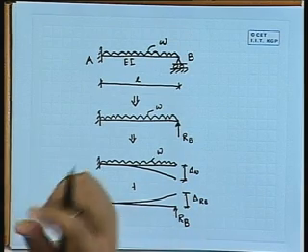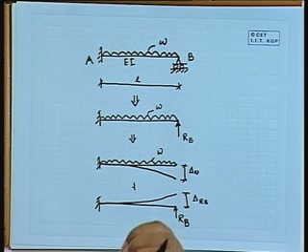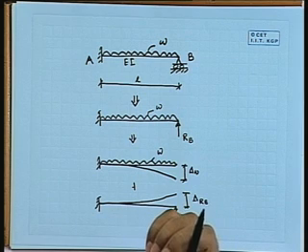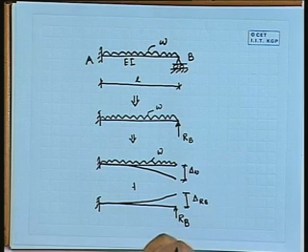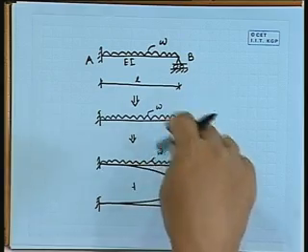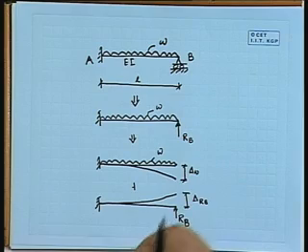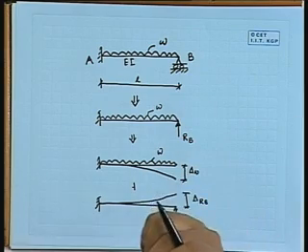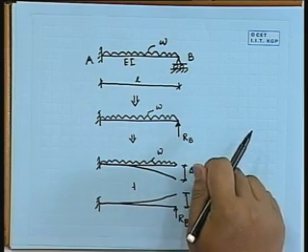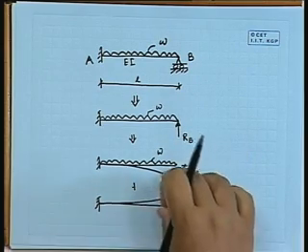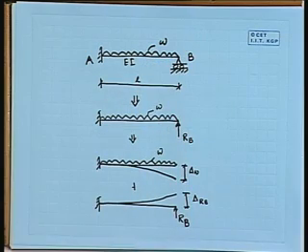These two values should be equal and opposite, because in a real structure joint B is connected to a support. So, it can't move vertically upward or downward. So, whatever delta W we get under W should be compensated by RB. So, if we take one as positive, the other should be negative. If it is 2 millimeter, it should be minus 2 millimeter. Ultimately, if we combine the whole thing, we should get back to the original situation where the deflection at B should be 0, right.